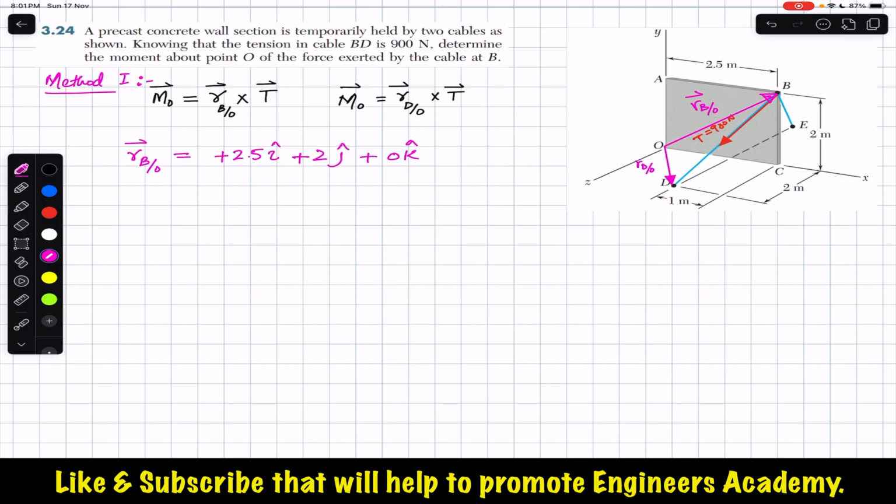Similarly, we can write r of t relative to O. Now we need to start from O and we need to move along the x, y, and z to reach that point D. So from O, we need to travel this distance. So this distance is 2.5 minus 1, which is 1.5. So we need to travel 1.5 meters in the positive x. And then in the positive z direction, we need to travel 2 meters distance.